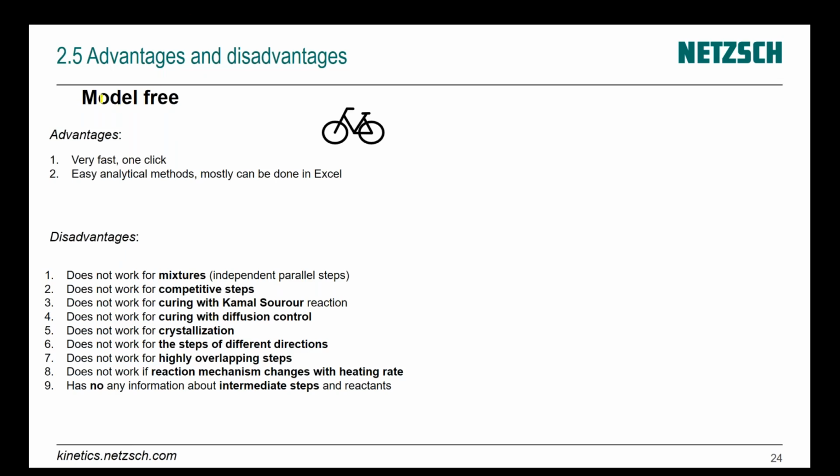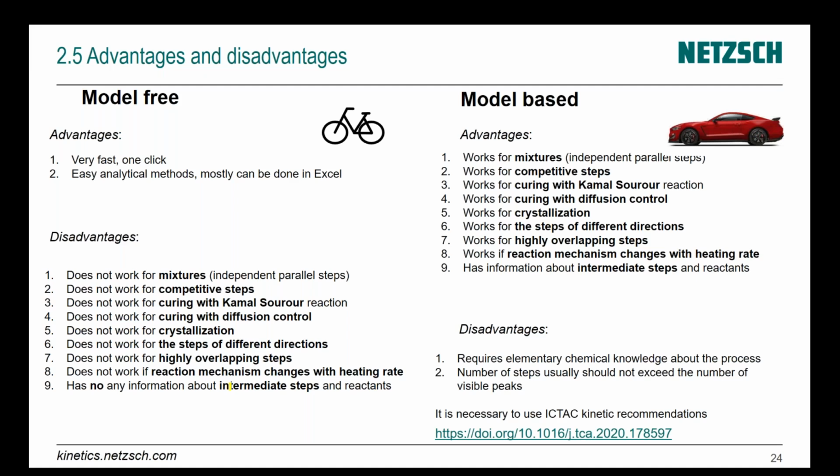If you speak about model-free analysis, it's like a bike. It's very fast, it's one click, it's easy to learn, easy to use, but it doesn't work for mixtures, competitive steps. It doesn't work for curing with Kamal-Sourour reactions, with diffusion control, crystallization, with steps of different directions, with highly overlapped steps. It doesn't work if the reaction mechanism depends on heating rate, and it has no information about intermediate steps and reactants. If we speak about model-based analysis, then it works for all these situations, but you need